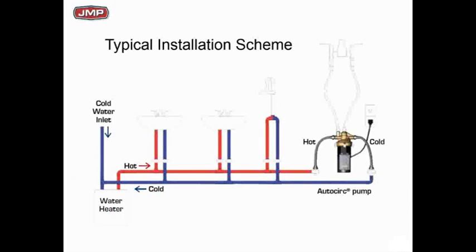So what the circulator has done is they're connecting the hot and the cold water supply to that last fixture into the circulator. There's a temperature sensor in that little circulator. If that circulator senses the set point, 105, 110, it cuts off.